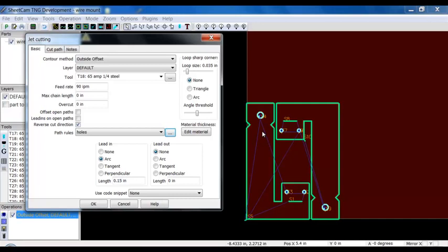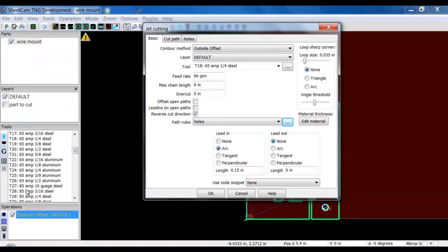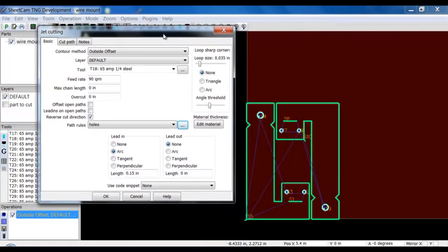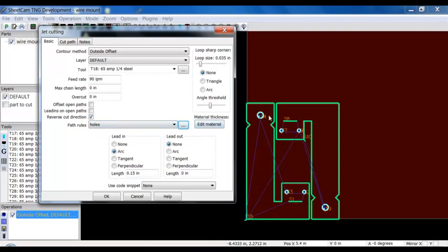Generally, when you're working with the default speeds that are set in the tools over here on your thicker materials, with really good nozzles, and if everything's set up right, you'll get good holes. However, when your nozzles and parameters aren't quite set perfectly, then your holes will be the first thing to deteriorate. Your perimeter cut will stay good while your holes don't quite turn out so well.